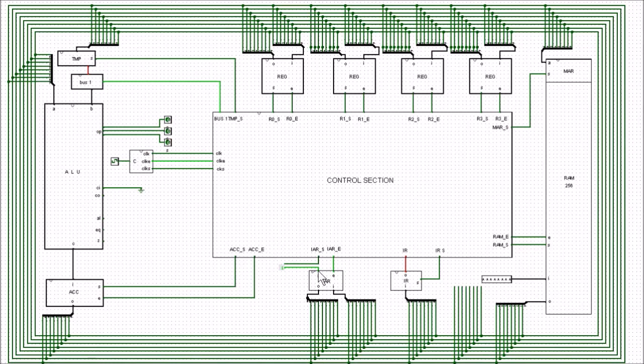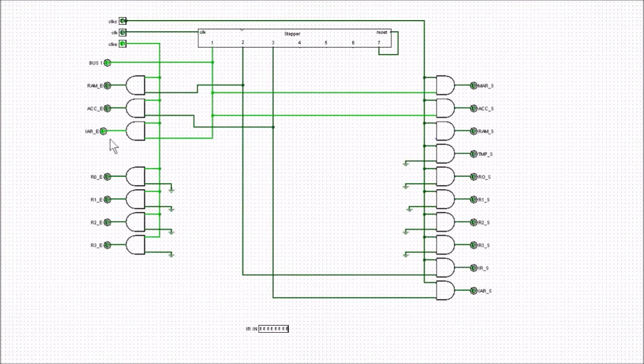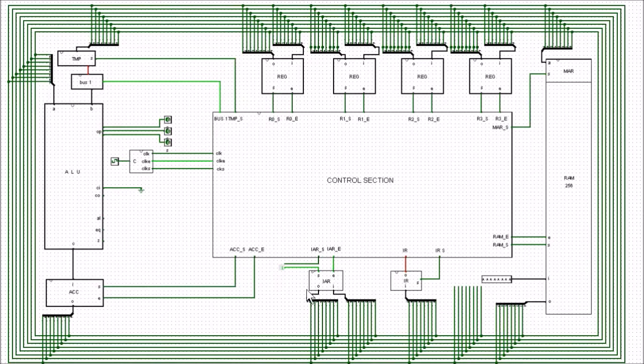Now secondly, you'll see that I've nobbled this as well, and I've changed the set here to high. And the reason we're doing this is that at the moment we don't have any reset functions within any of these registers, so in order to get the initial conditions correct for the moment, I'm just having to put the set to a value of high. Okay, so that's just an initial condition, and whenever we work our way up the hierarchy, a reset function will be provided. But at the moment for this simulation we just set that at high. Now when that's set at high, we see that when we get into the control section, right away the instruction address register is enabled. So it means that the value that's in this instruction address register is automatically now placed onto the bus.